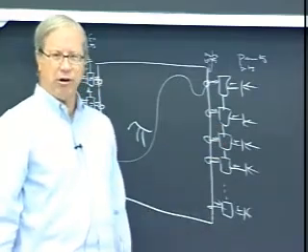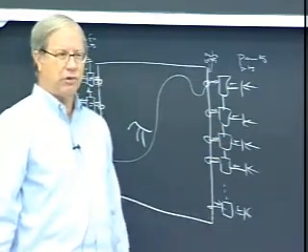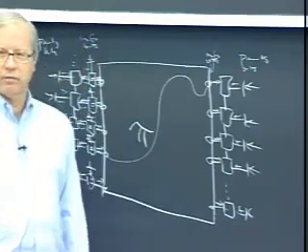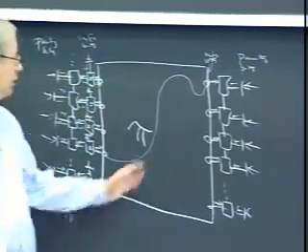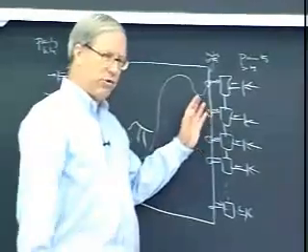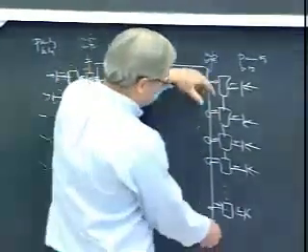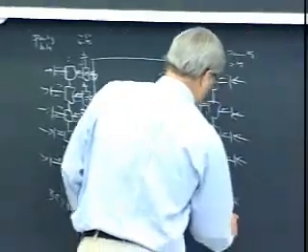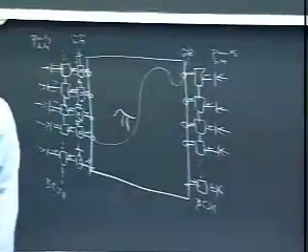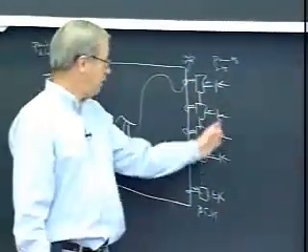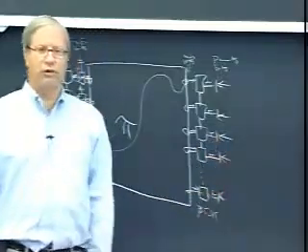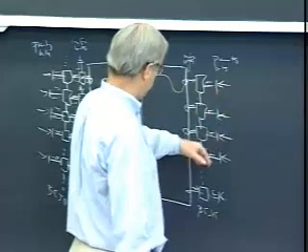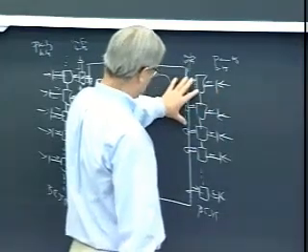All right, they tell you more about the information bits than you got just from looking at the raw data from the channel. All right, that's basically where turbo comes from. You then do BCJR over here using this improved intrinsic information. Of course, the parity information hasn't improved. You might think of ways to improve this too, but this was the basic scheme.